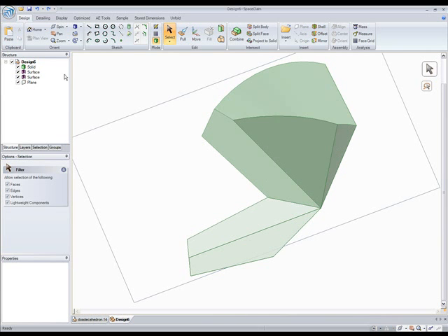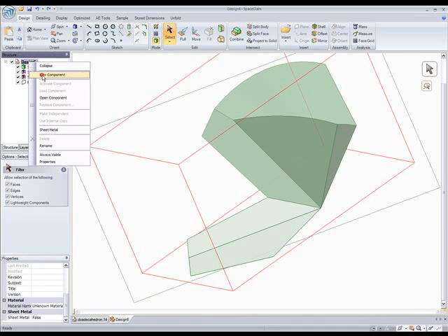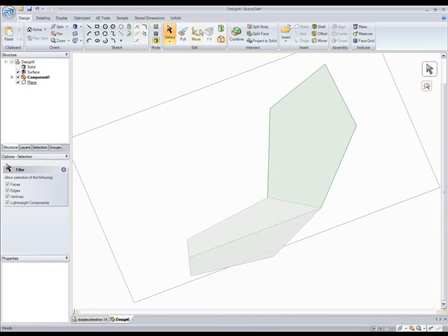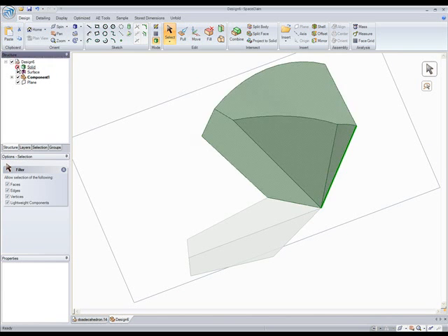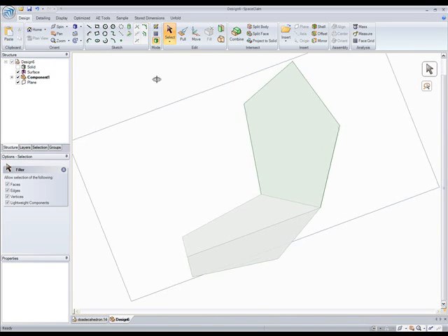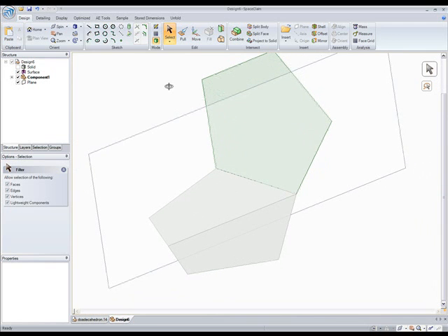And I'm just going to take that pentagon in the back, and this is a useful technique I use all the time, which is to put part of my model into a component and then use assembly techniques to get something exactly where I want it. So we'll make those two edges coaxial with each other, and then I'll grab that edge and snap it up onto there, and now we can hide our solid, and we have these two faces at exactly the right angle.